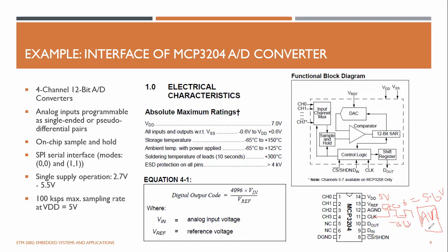Minus voltages are possible. When you command these grounds, there could be a voltage drop in these lines, and the grounds are not the same as this one, right? So in that case, there could be some negative voltages applied, but make sure you use short wires and never take your signals below minus 0.6. Otherwise, the device will fail.